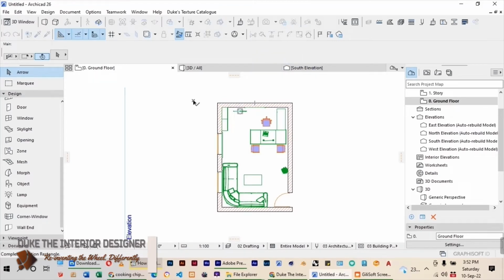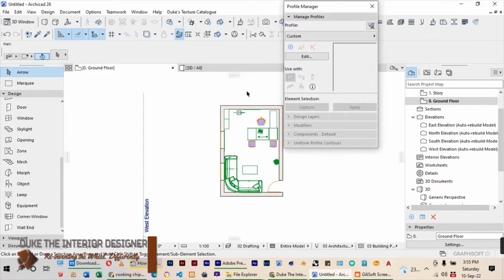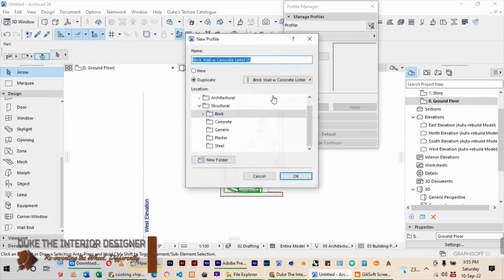Then after putting the floor, we need to do the skirting. Skirting is important. I'll use a profiler. Go to new. I want to place it under architectural. So I'll give it a name. Office skirting. That would be new.